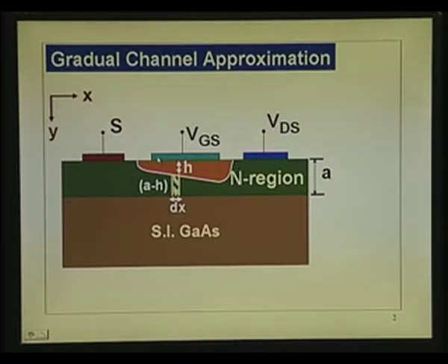But as VDS becomes larger, current becomes larger. We saw ID is proportional to VDS and it is linear initially. Now, how long will it be linear? That is what we want to see, and what happens if we keep on increasing the VDS. As we increase the VDS, the current increases and the drop increases, and if the drop increases, the potential across the depletion layer changes.